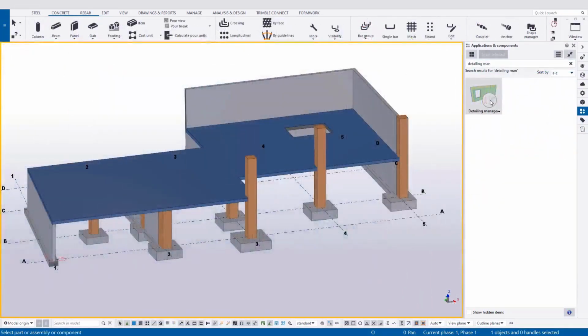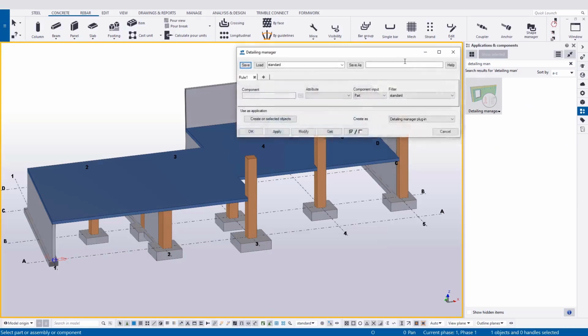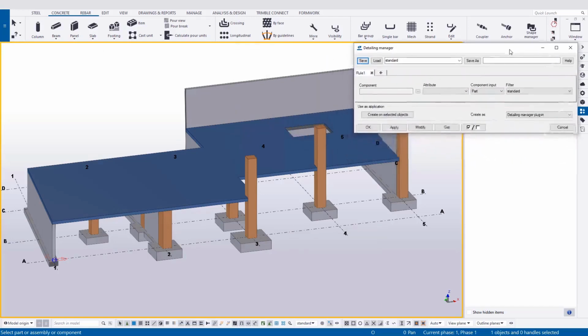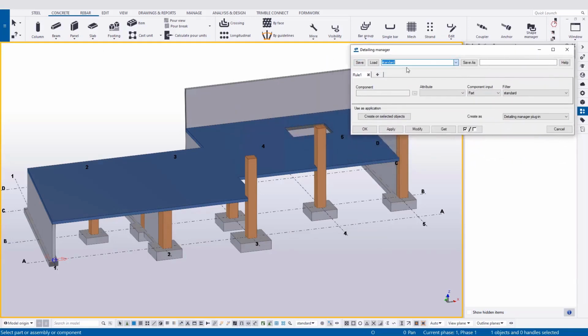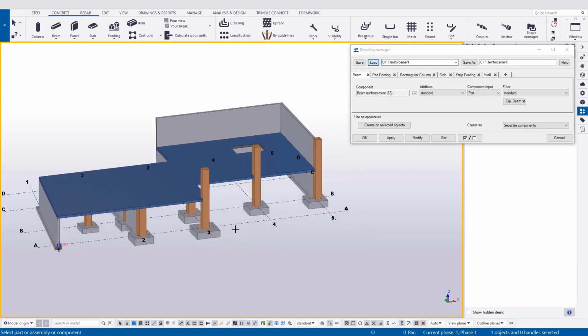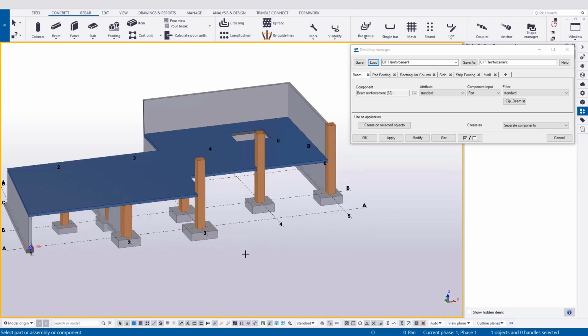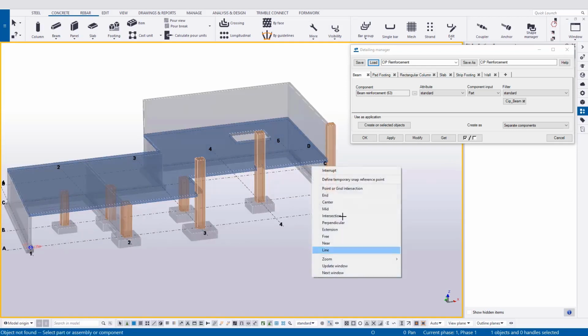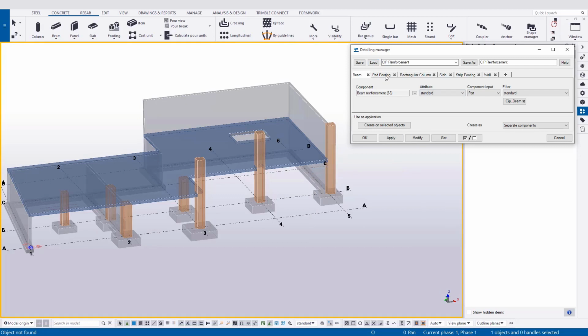Now, the Detailing Manager is an application that utilizes components and applies them en masse. Within the application, detailers establish a tab per condition they would like to reinforce, then select the component and associated save setting to apply to the concrete. The application uses filters to sort out what applicable pieces of concrete will receive this component and which ones will not.